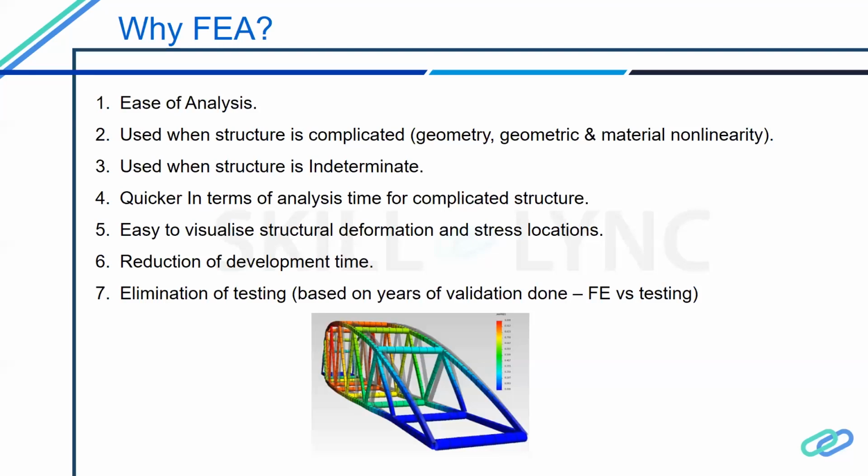Once you build the galley, they put the entire galley into the test rig and apply the loads. Then we monitor what load reactions you get at the upper attachment and lower attachment, and you correlate the test results with the FE. If the test results are within acceptable margins, then you declare that the test you have carried out is valid and can be used for certification.